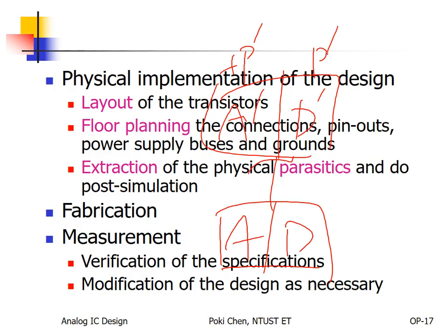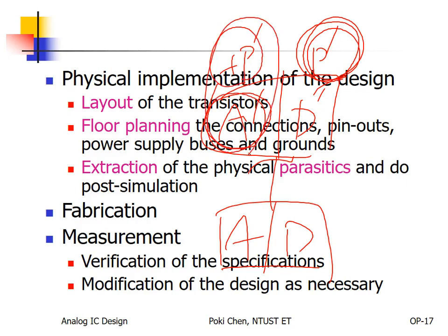Your simulator will waste most of the time on such parasitics. How to speed it up? The analog equivalent circuit and parasitics dominate the accuracy, and the digital one only slows down your simulation.